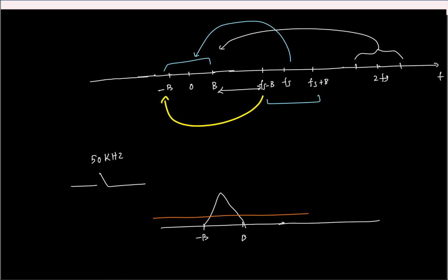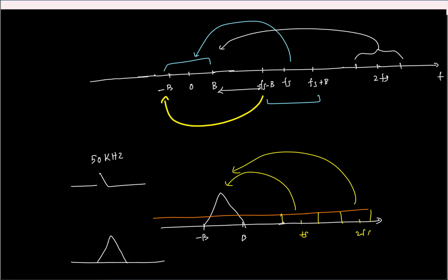So, by the same logic, this band of frequencies around Fs, 2Fs, 3Fs, everything will sort of alias back, right? And after sampling, what you will see is, you will have the signal of course, but it will completely get drowned in noise, right? You will not be able to recognize the signal at all because you have aliased so much noise that the noise is dominating the signal. Is that point okay?